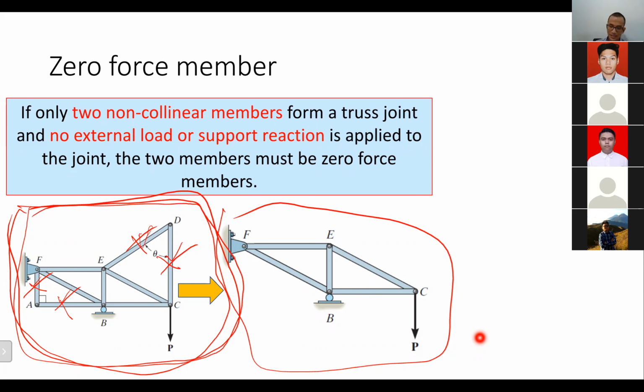But sometimes there is another condition where it is necessary for those members to be there. Do you get it? So later, when you have a design, then you analyze, and it's zero force member, zero force member, zero force member. Then you delete all, and in reality, you don't put them there. But in order for you to do so, you have to consider all the possible loading. Azhar, do you get it?